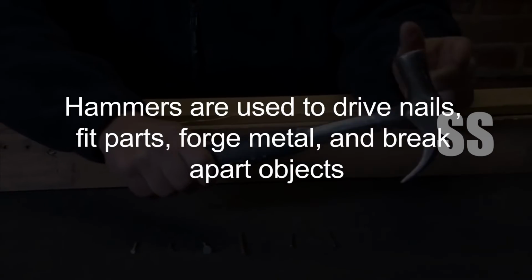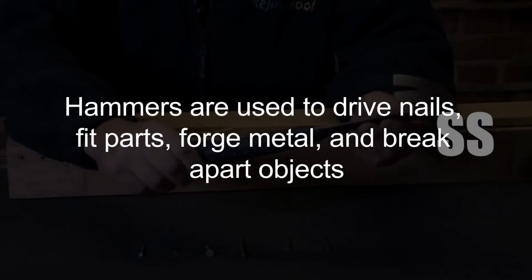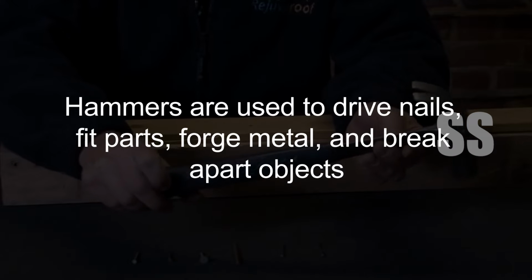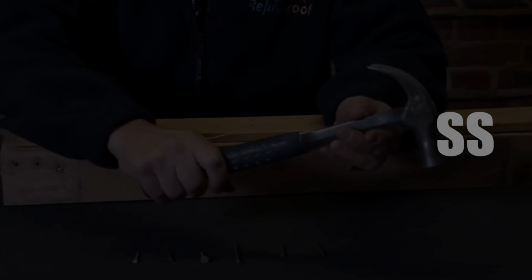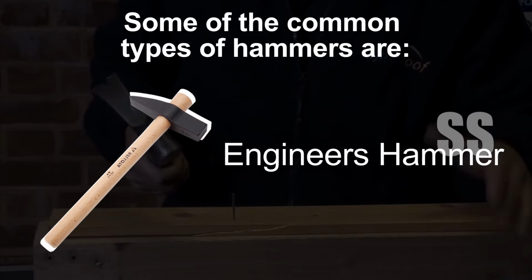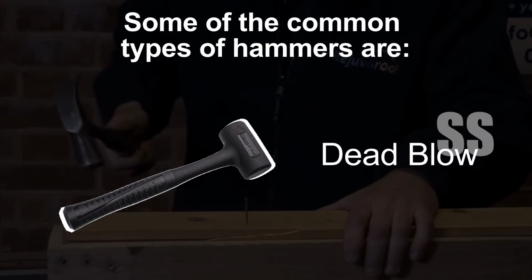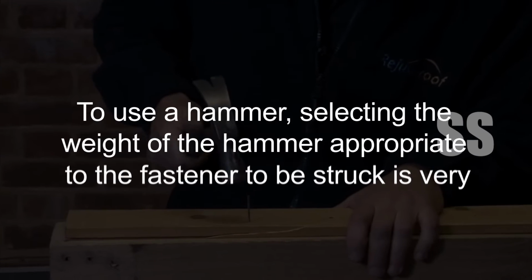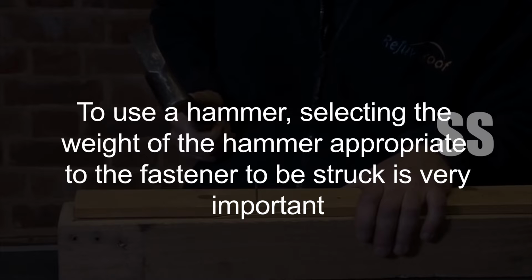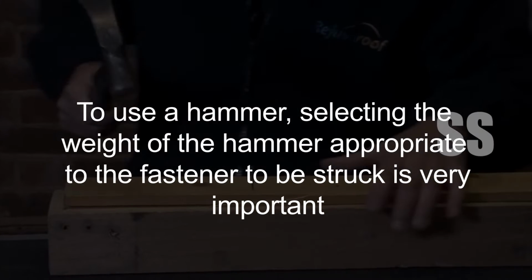Hammers are used to drive nails, fit parts, forge metal, and break apart objects. Some of the common types of hammers are ball peen hammers, engineer's hammer, soft face, rubber mallet, dead blow. To use a hammer, selecting the weight of the hammer appropriate to the fastener to be struck is very important.